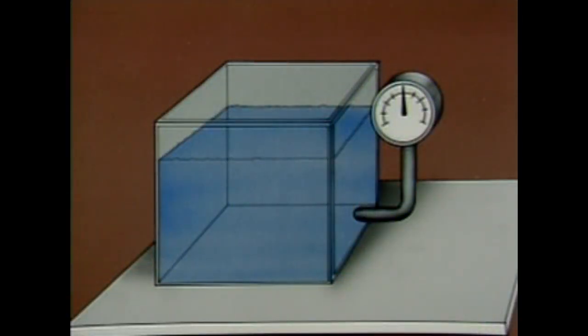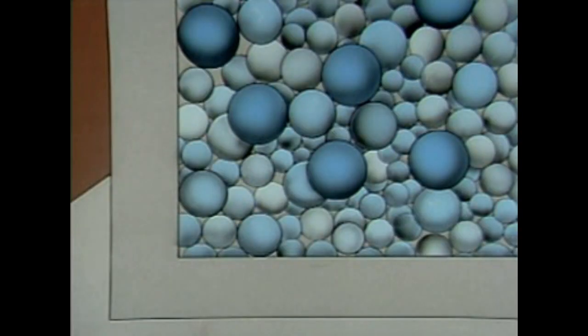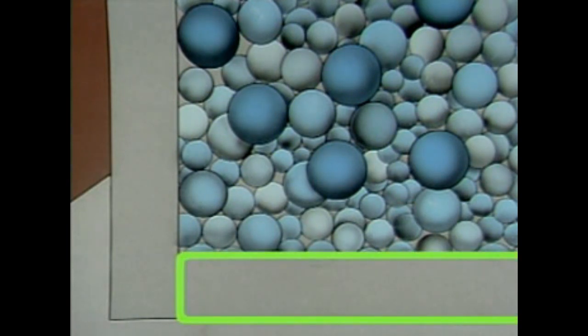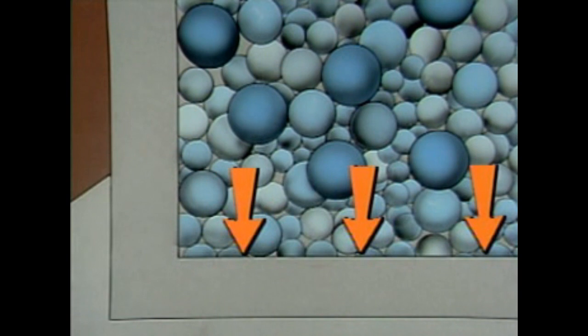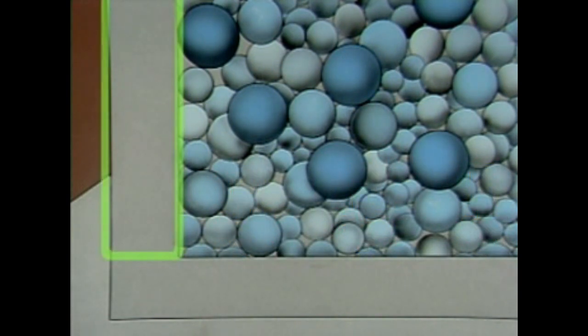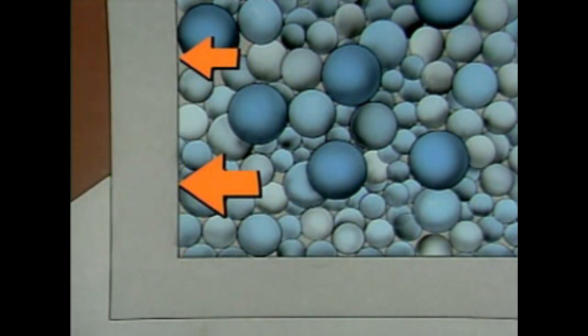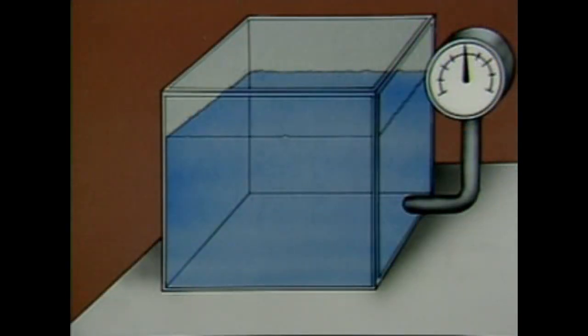By definition, pressure is force applied over an area. In an open container, pressure is affected primarily by the weight of the liquid applied over a given area. These circles represent liquid molecules. If we focus on the bottom of the container, the pressure exerted there is the total weight of the liquid divided by the area of the container's bottom. The pressure exerted on the side of the container is a result of the force of the liquid pushing outward. The force pushing outward is a result of the weight of the molecules above. This means that the pressure in a liquid varies with its height or depth.